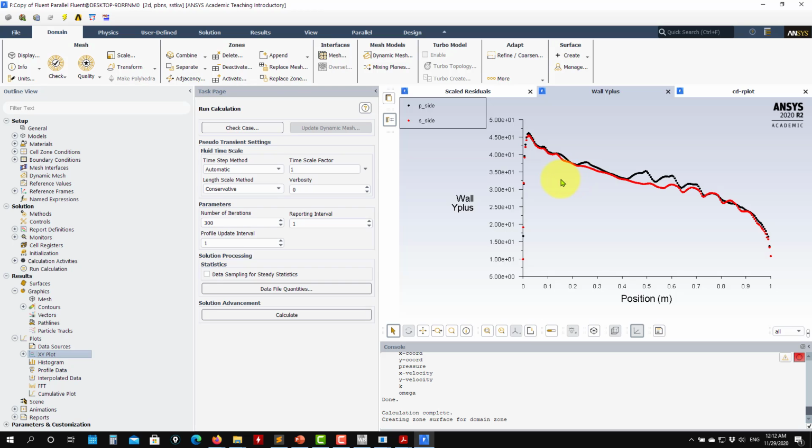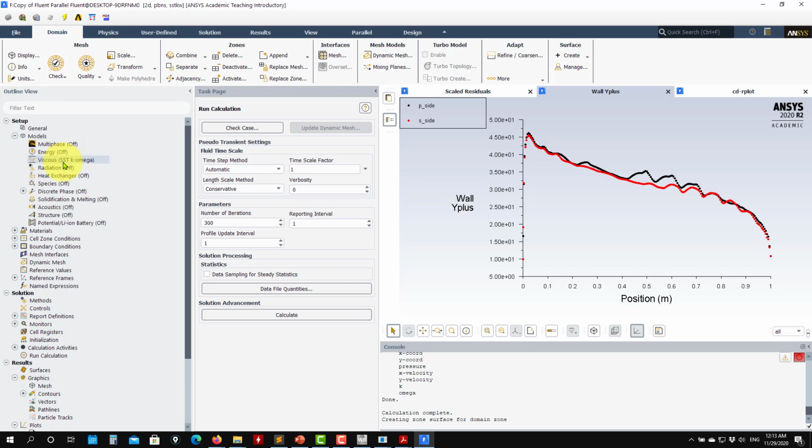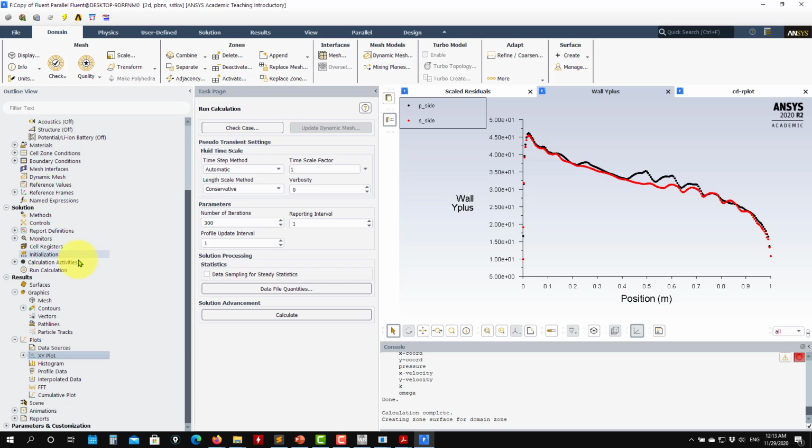So this is it. This is how you do the simulation. You have the recipe to run your airfoil and compare. Something important: I'm not expecting a perfect match with airfoil, but the value should be close. Okay, close. Now it's 0.35, 0.32, okay, but I'm not expecting a perfect match. I just want you to get the feeling of CFD simulations, to see that it's much more complicated, and also to know that you have this turbulence tab here, and turbulence is extremely important. It is what is going to change everything in your simulation.